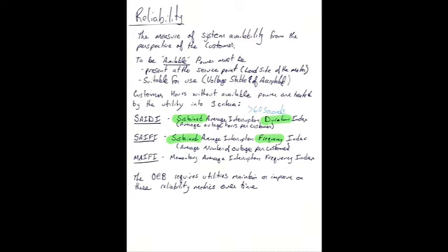And we do track how many momentaries there are, although the utility is not held to account for having a large number of momentaries. And in fact, one of our objectives in this course is to try and figure out how we can convert an outage that was going to be permanent and resulting in a truck roll and a lot of investigation, and turn it into a temporary fault that resolves itself. And so we have momentary outage tracking as well here, which is less than 60 seconds.